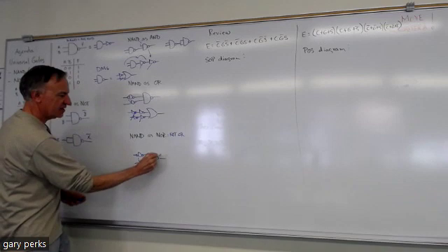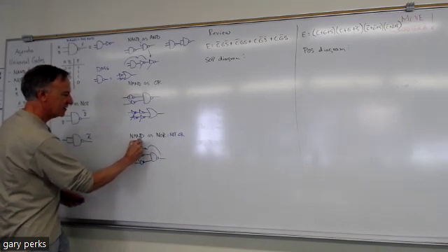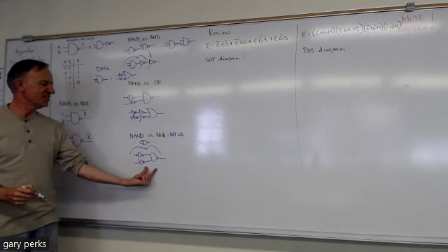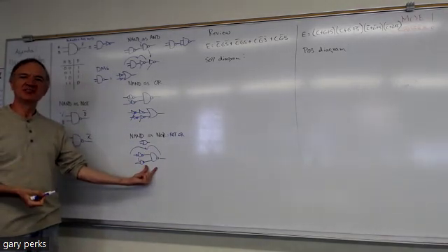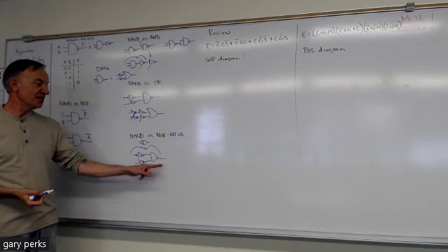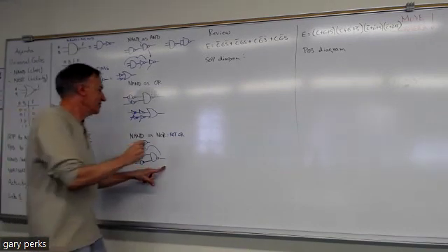Right, so this right here is the same as an OR gate. Right, because that's what we did right up here. So if this is the same as an OR gate and I want to make a NOR, what would you do? And NOR means not OR. Yeah, just put a NAND gate as an inverter on the output.